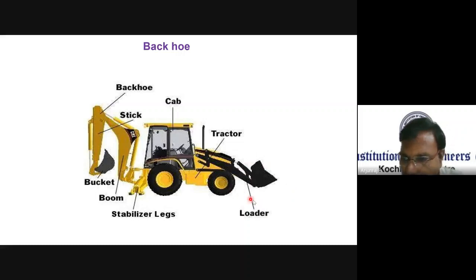If you use the softer material bucket to handle hard material, then the tooth, which is a part of a bucket, will get damaged, and that will be a big loss. So you need to select the bucket, and accordingly you can go for a cost reduction and also optimize the cost. That is also a good way.